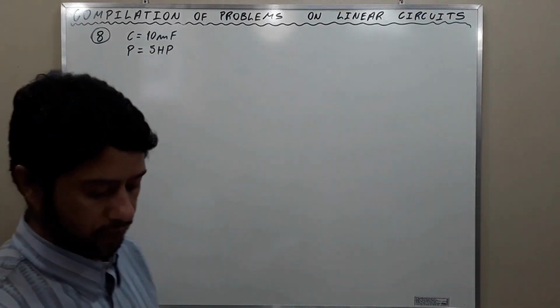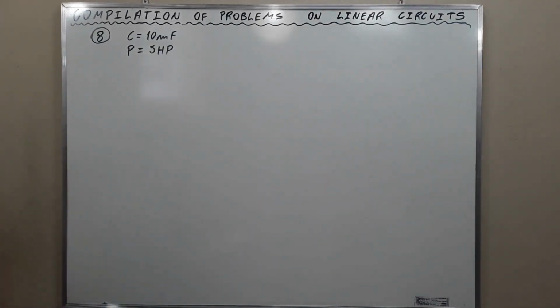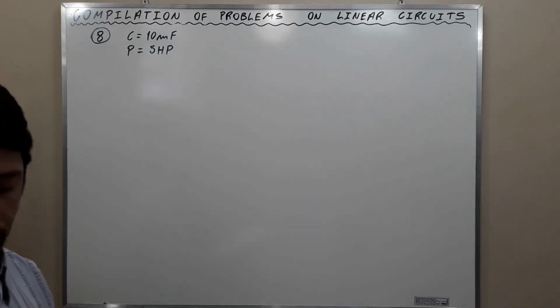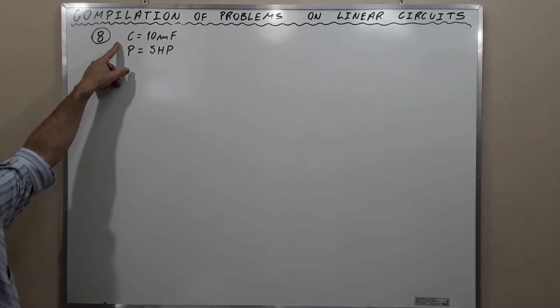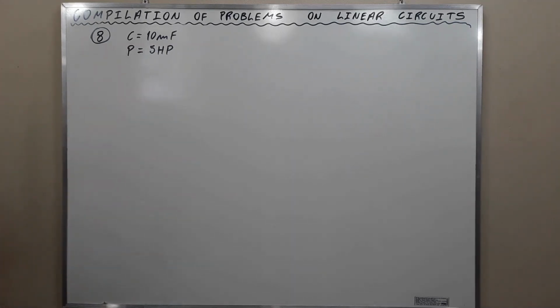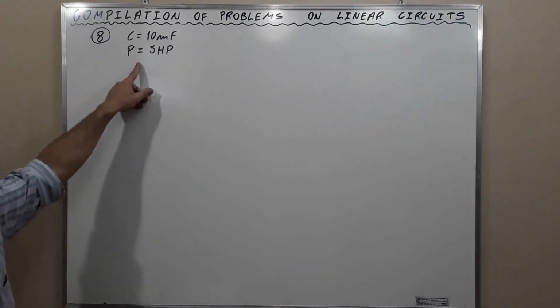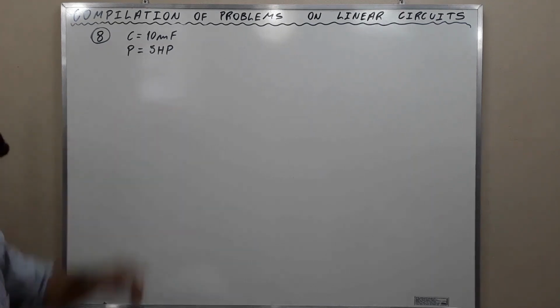Question 8. We want to store sufficient energy in a 10 millifarad capacitor to supply 5 horsepower to an automobile for 1 hour. To what voltage must the capacitor be charged?